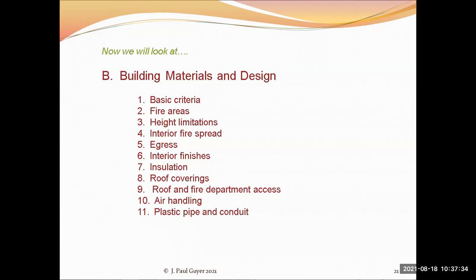And a key point in fire protection engineering is that a person is somewhere in the building and a fire breaks out somewhere else. Like, as an example, a person is in the building, a fire breaks out on the left. Well, if the only egress route that that person has is to the left, he can't get out safely because the fire is blocking him. That's why in building design, you always want the occupants of the building, no matter where they are located within the building, to have two ways to get out of the building in the event of a fire. So fire breaks out on the left, occupant can't get out by going to the left, but he can get out by going to the right.